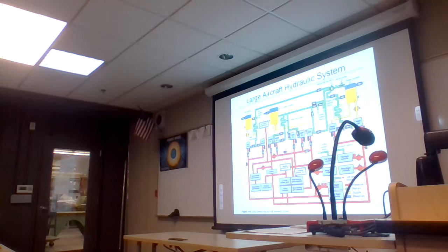I don't know if it has a PTU in it. I guess it doesn't. But they have a different pump that allows for taking fluid from one reservoir and routing it through a combination pump and motor in order to supply hydraulic flow. And it does it all without really stealing fluid from a particular system. It just attempts to repressurize a system that's lost its pressure.